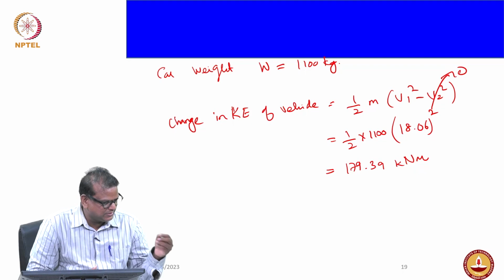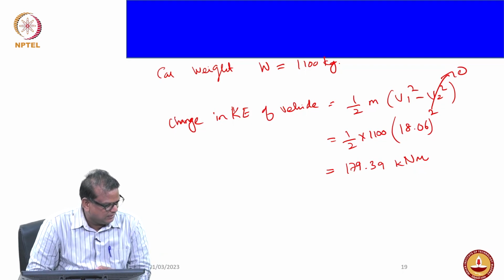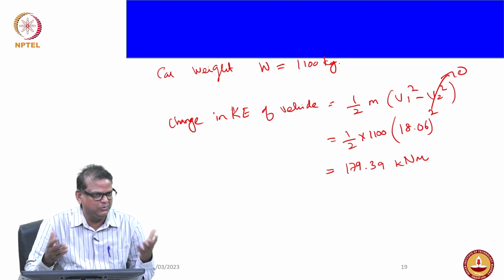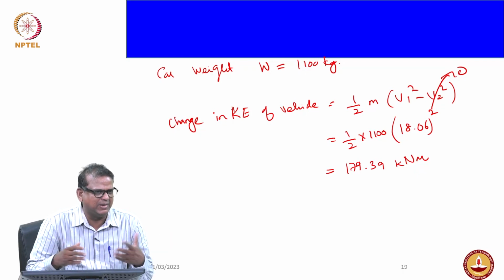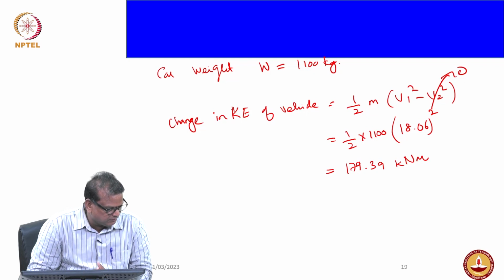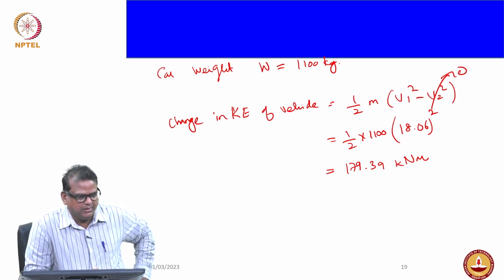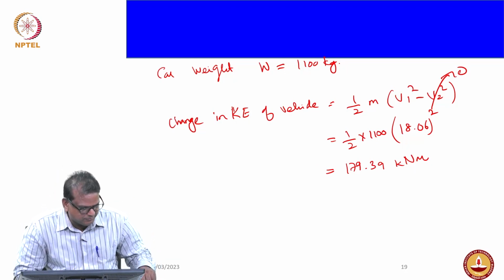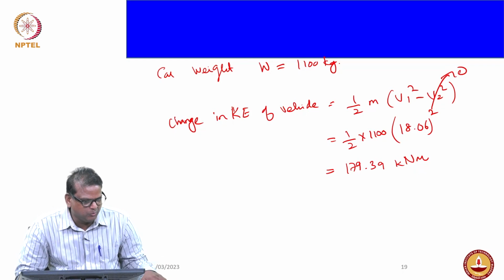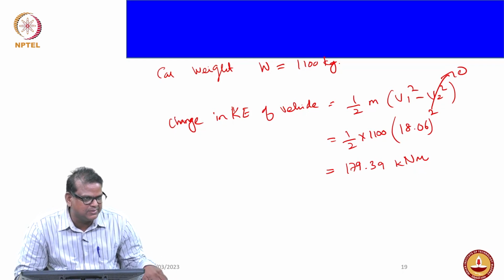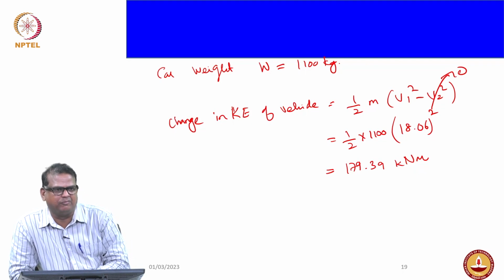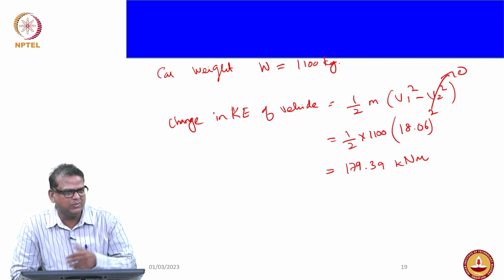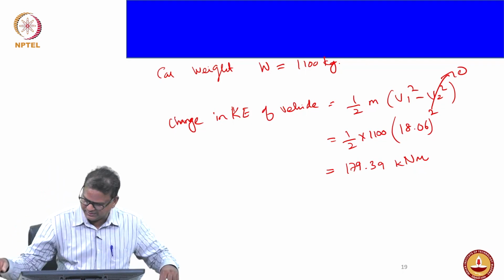So that is the precise reason they said kinetic energy of moving parts. You can usually take it in percentage terms, maximum 20%. It varies, depends on the size. So 10% of the vehicle you can assume for the moving aspects. In fact, when we do a problem, we have to find out precisely how the moving parts' kinetic energy would affect the brake performance. As we move on to the lectures, we will understand that aspect as well.